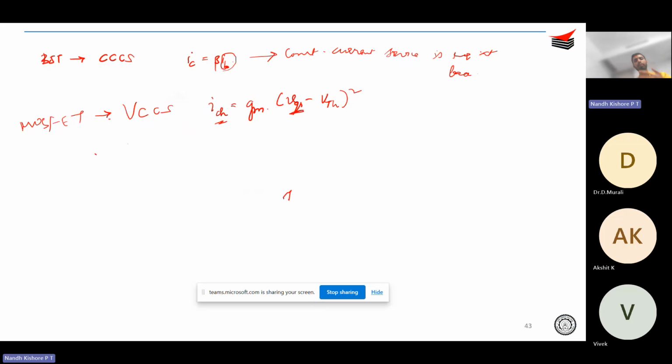So basically you can have the CGS capacitor getting charged up, right? If you charge up the capacitor, that's enough. I need not have a continuous IG current. I just need an IG current profile, something like this. It can go zero during the rest of the periods. I just need a peak IG current to charge up this capacitor, and a peak negative IG current to discharge this capacitor.